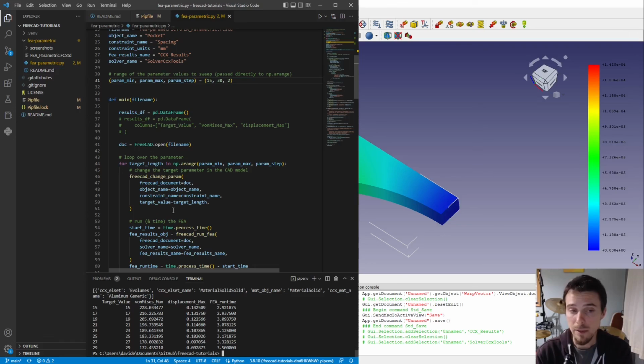You can have a bit more fine control over what parameters you get out, and over plugging in your own calculations, say if you want to do a fatigue criterion where you need maybe the principal stresses and recombine them in certain ways.